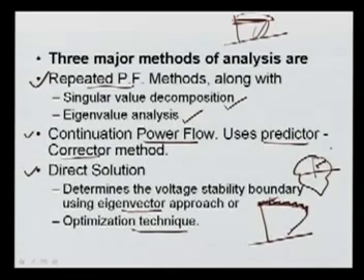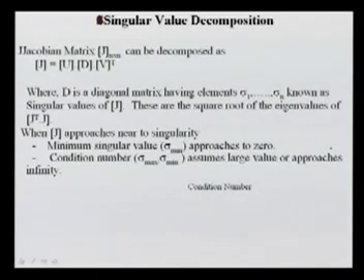Now let us see the first one, the singular value decomposition technique, which is very popular and can be used widely. Here, for the complete Jacobian matrix, if you have an n bus system, you can form the Jacobian matrix of order n cross n, which can be decomposed into this form.